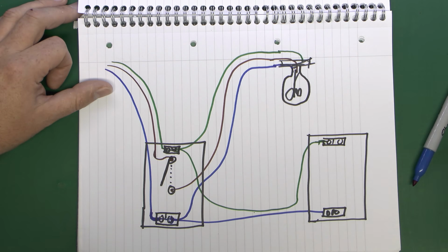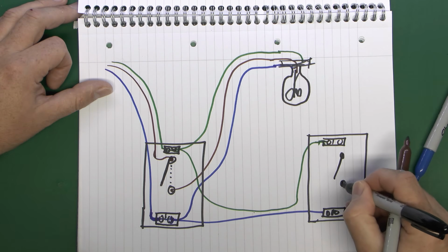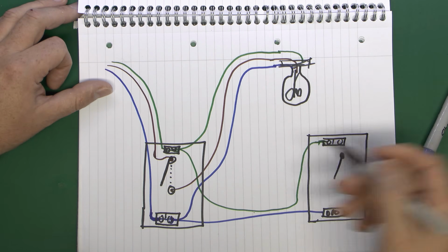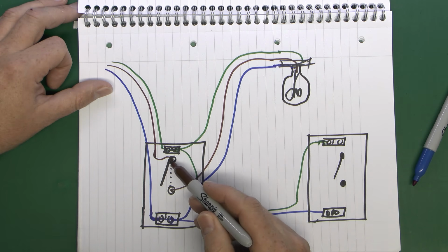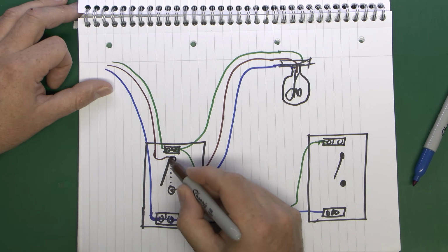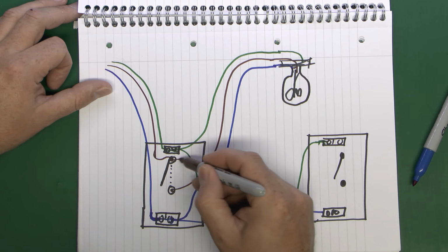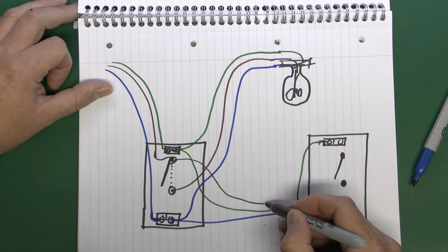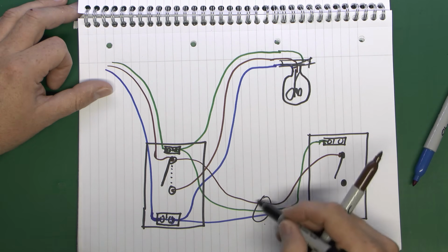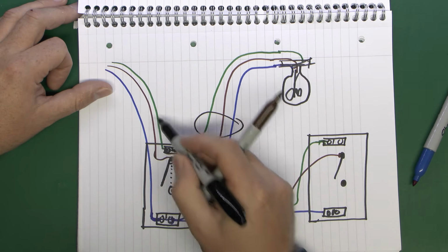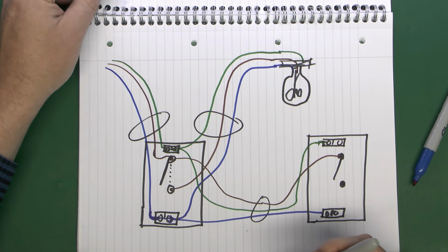And the line, again we can have the switch here just as before. Now the line, it's important to get the correct one here, because we want the one that's coming in from the consumer unit, so the one that's permanently connected to the power. And in that case it's going to be the top one here. So that would come out of there, part of the same cable, and obviously go into the switch there. So here's one cable, there's the other, and that's the third one. So the same 3 cables as we had previously.